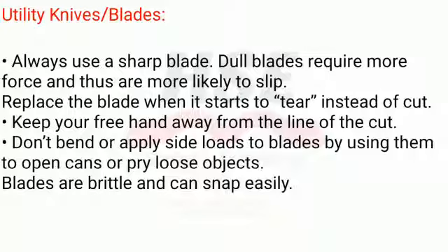Utility knives/blades. Always use a sharp blade. Dull blades require more force and thus are more likely to slip. Replace the blade when it starts to tear instead of cut. Keep your free hand away from the line of the cut. Don't bend or apply side loads to blades by using them to open cans or pry loose objects. Blades are brittle and can snap easily.